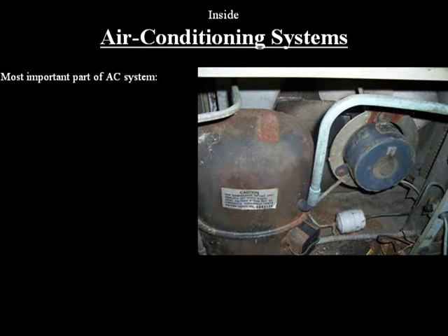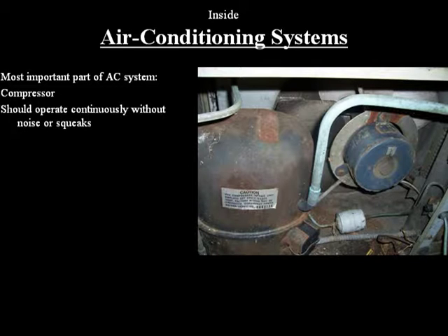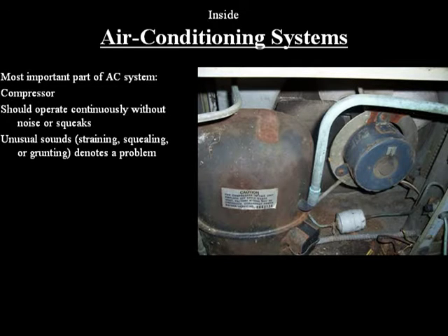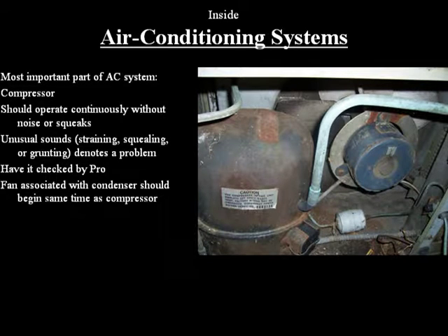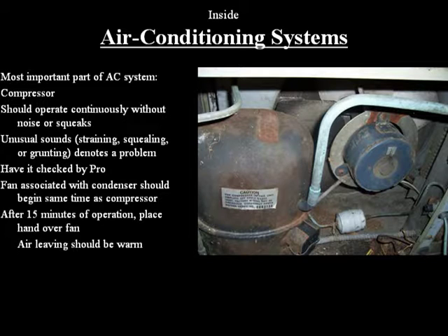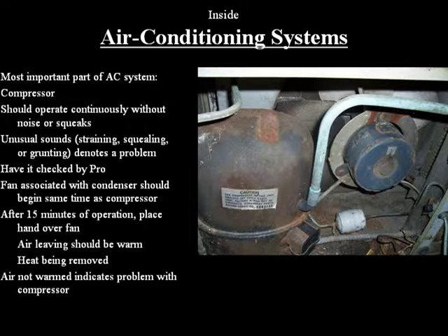The most important part of any air conditioning system is the compressor. This should operate continuously without any noise or squeaks. Unusual sounds heard, like straining, squealing, or grunting noises, denote a problem that should be checked by a professional. The fan associated with the condenser should begin at the same time as the compressor. After about 15 minutes of operation, place your hand over the fan. The air leaving should be warm, as the heat is being removed during the compression of the refrigerant. Air that is not warm indicates a problem with the compressor.